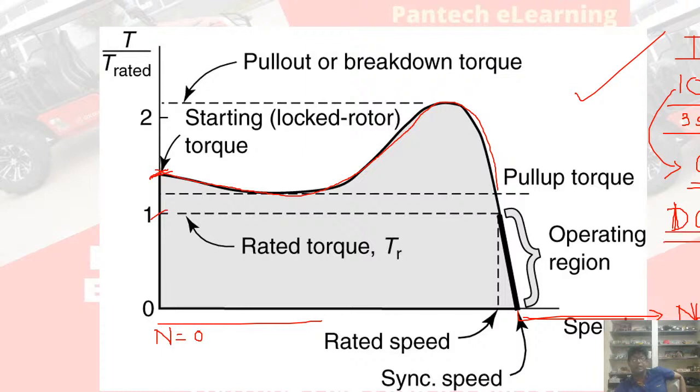So naturally, to mitigate this, if your motor rating is 10 kilowatt, you have to design or identify a source which can deliver 60 kilowatt for 2 to 3 seconds, because during the starting the current requirement is 5 to 6 times.